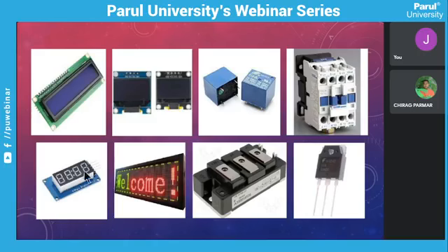The 7-segment displays are mainly used in the voltmeter. I mean to say, if you see an electrical panel, you will see many different displays indicating the voltage between the two phases, the main voltage, and every other thing, the frequencies, whatever you say. If you go into the other switching sections, you may see a tap position indicator displayed by the 7-segment. An AVR, automatic voltage relay, voltage control relay, then an OTI displaying temperature. Many things.